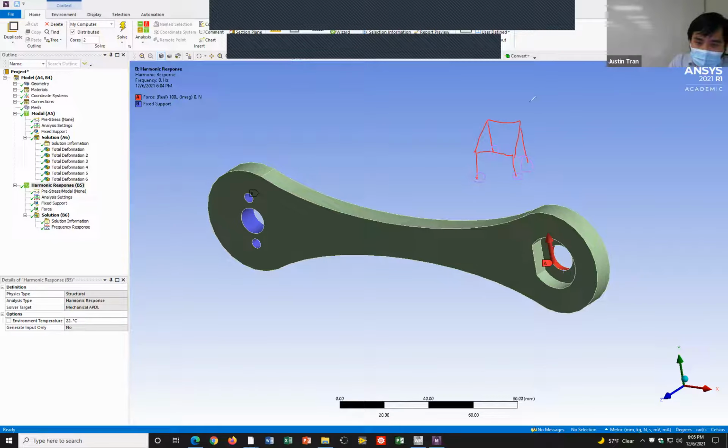And so a couple ways you can do this. One way is you can keep the bottoms fixed, but apply the oscillatory force on the first floor or at the tops of the columns if you want. Another kind of clever way is that instead of applying an oscillatory force, you can apply an oscillatory displacement. Okay, and so here's our one-story building here.